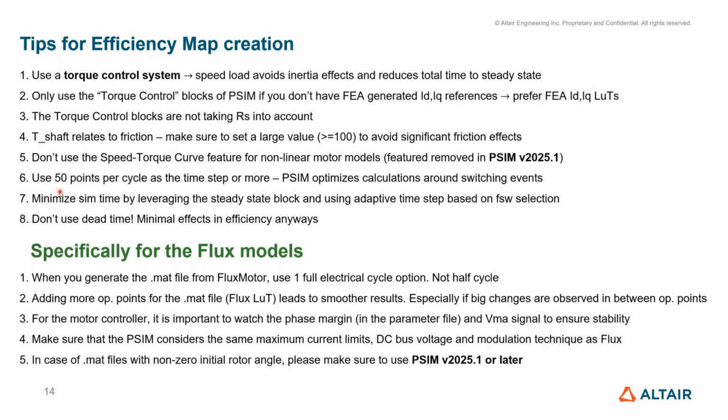Now, when it comes specifically to Flux, I want you to be cognizant that the new PSIM version that is coming this month, version 2025.1, will bring a lot of updates and fix some issues we have when the lookup table from Flux includes a non-zero initial rotor angle. So if you watch this webinar at a later time, please work with PSIM 2025.1 or later, to ensure that you will have a smooth experience.